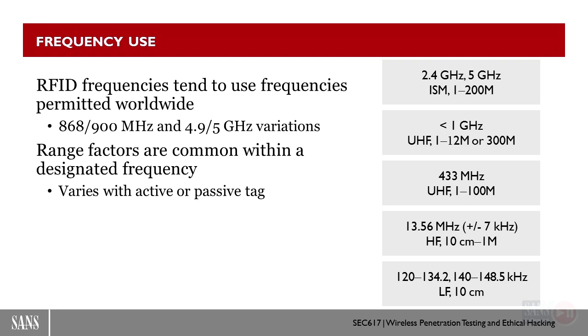Typically, the high frequency and the low frequency tags down here in the bottom are going to be passive, meaning they have no battery. And we'll talk about how we get power to them. And typically on the UHF and the ISM band ones, there is some sort of power with a battery and may engage in a hybrid-based approach for when it receives some signal to power up and then emitting at higher power after it sort of received that initial kick to turn on. So we'll talk about some of those.